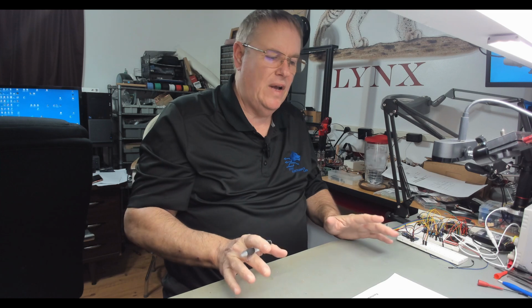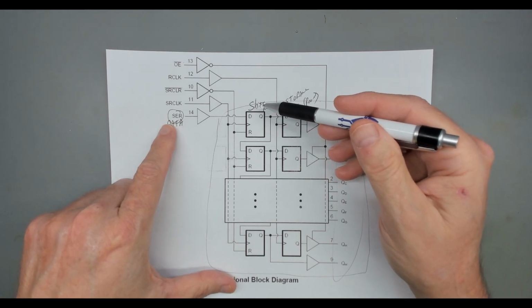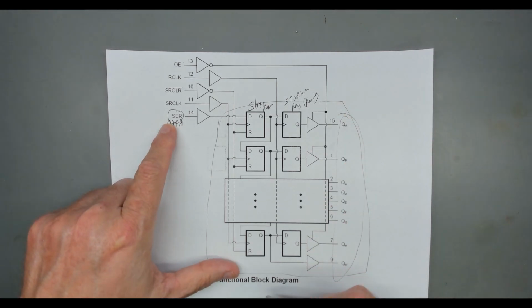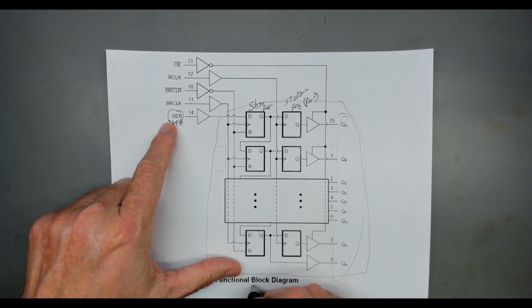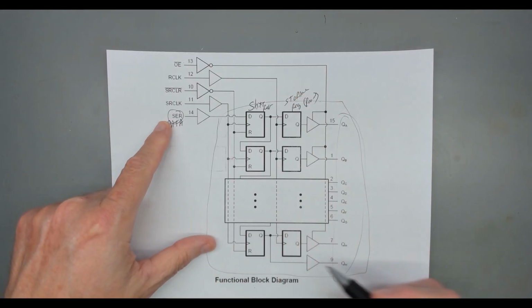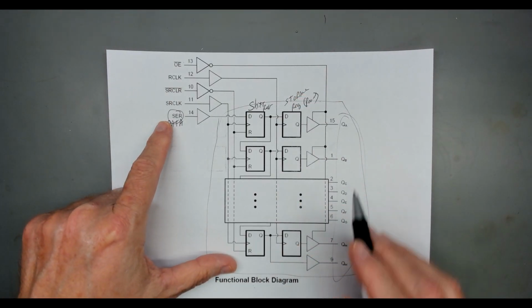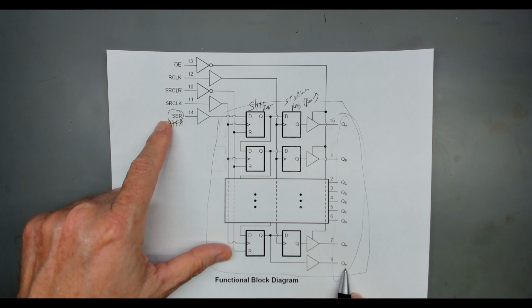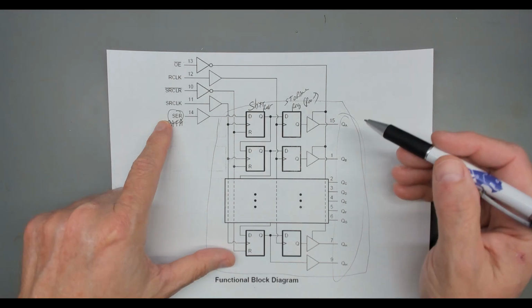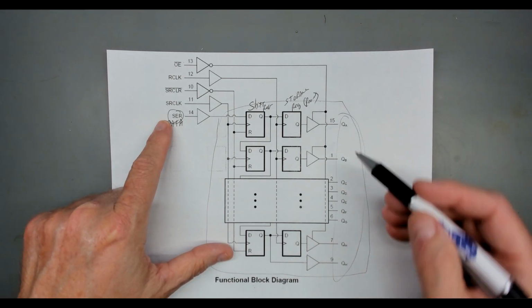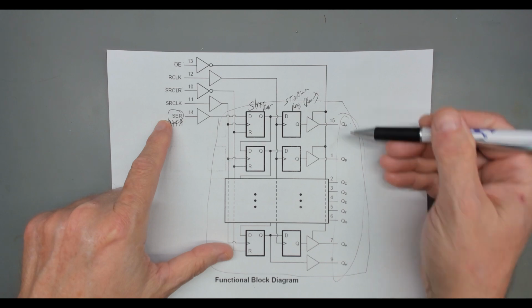So now how does this all work together? Well, it's fairly simple. You have to understand you put the data in for the very bottom register, register 8 on this chip. You put that data in first. Keep that in mind: the most significant bit goes in first. We go all the way down to number 8, which is 7. It's 0 through 7. Actually, they call it letters. So you go all the way down to H. You've got A through H.